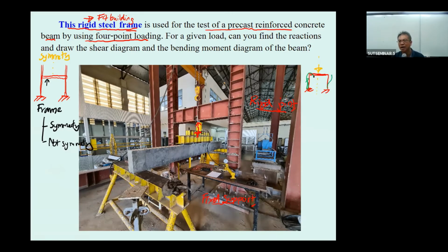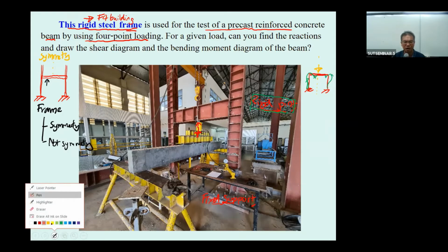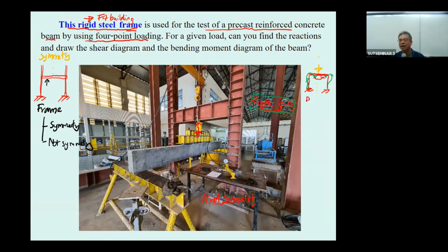And then over here we keep the 90-degree angle, and we also keep the 90-degree angle over there since the joint is a rigid joint. So the deformation of the structure will be in symmetry. The degree of freedom of this frame will be, let's say this is A, this is B, this is C, this is D. We will have only theta sub B, and due to the symmetry, theta sub B is going to be minus theta sub C.